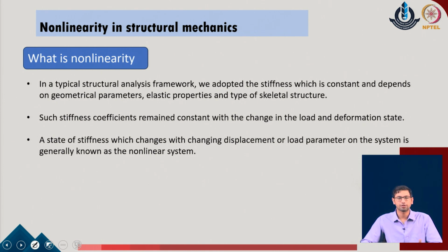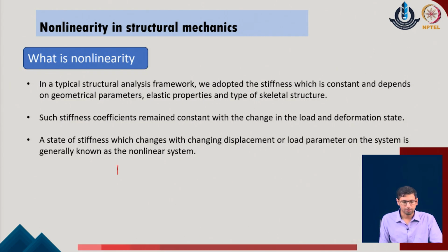Before going into it, we can realize that in the regular problems of structural analysis which we have followed till now, the equation at the end of the formulation was written in the form of A, which is the action field of the given structural component, equal to the structural stiffness of the system times delta, which is the deformations of the system. Many people write it as P equal to K delta, where P is the force, K is the stiffness of the given system, and delta is the unknown displacement parameters of the problem.